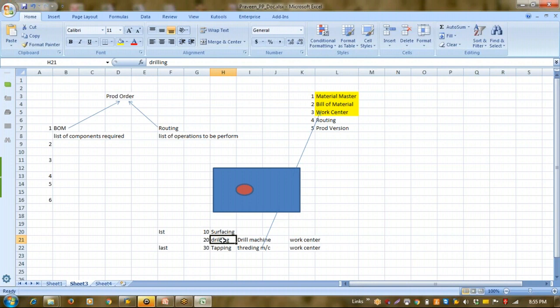Generally the most commonly used inspections are for incoming raw material, in process, and post production. So if you divide your total process into tiny operations, then you can do this kind of in-process inspection. This in-process inspection helps you to produce a good product, or we can say it helps us as a quality control tool.